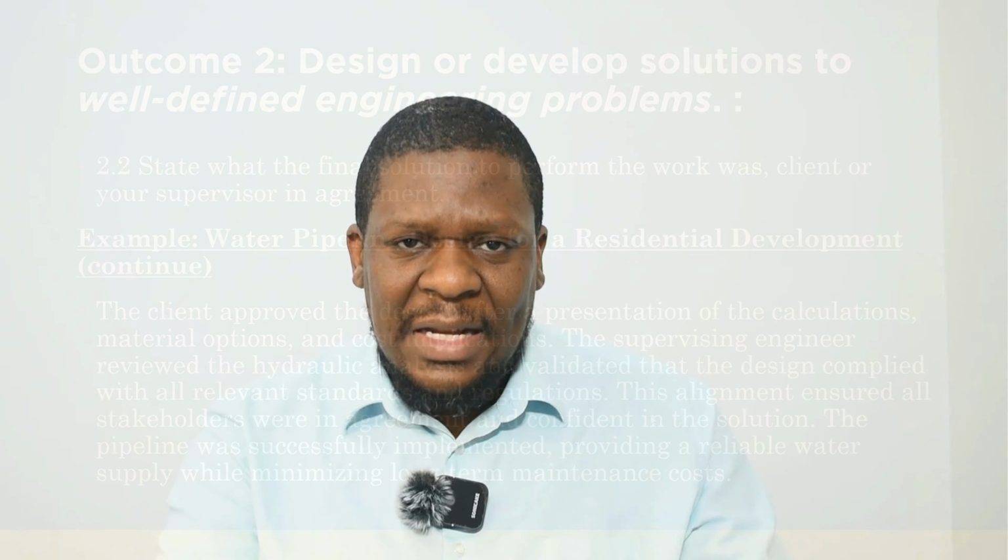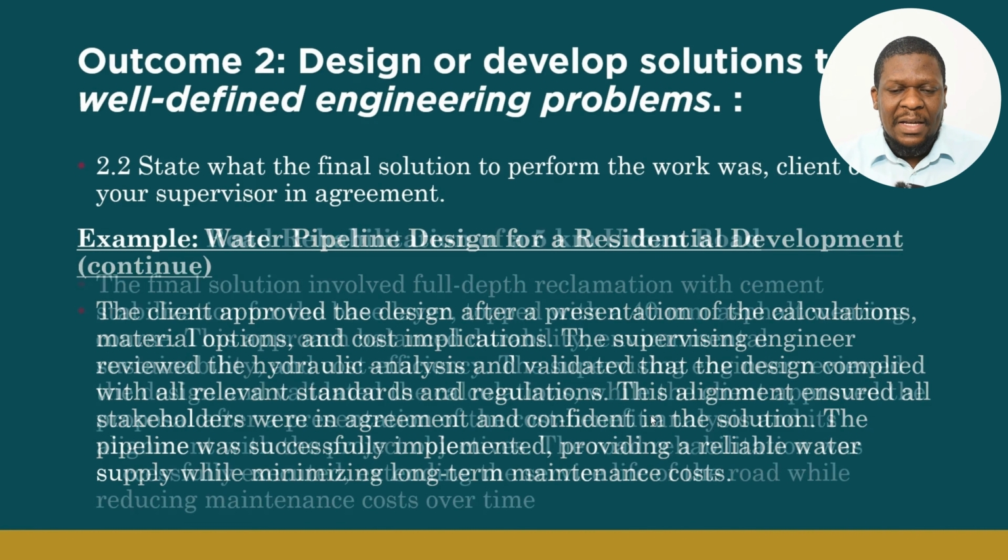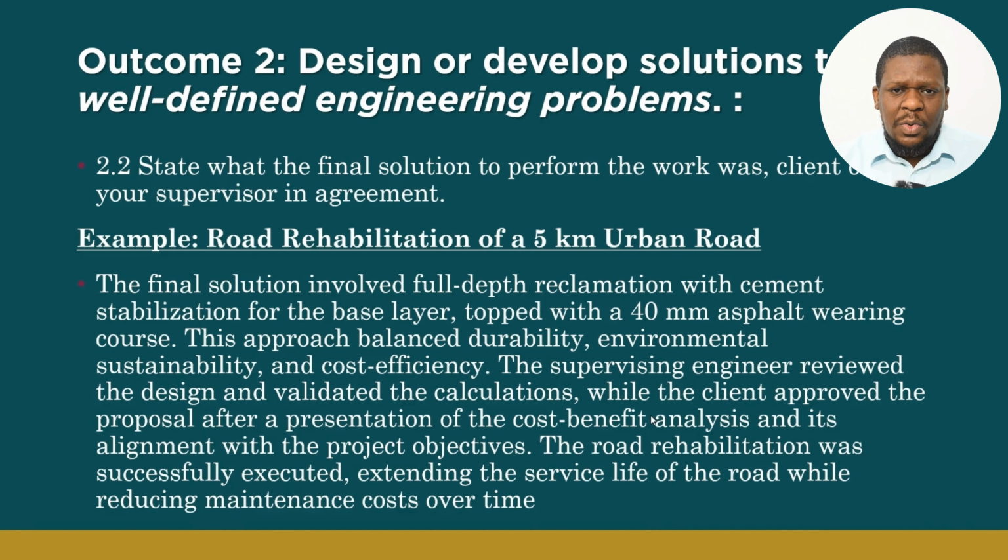You were presented with a problem, you came up with options and eventually chose one solution and presented it in a logical way for the client and for your supervisor to be able to understand. That is what is expected of the applicant. Rehabilitation of the road. The final solution involves full depth reclamation with cement stabilization for the base layer, topped with a 40mm asphalt wearing course.